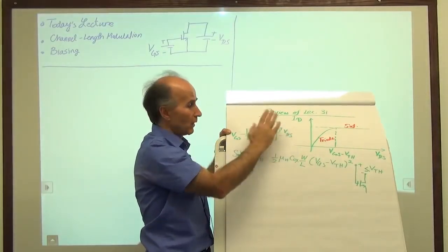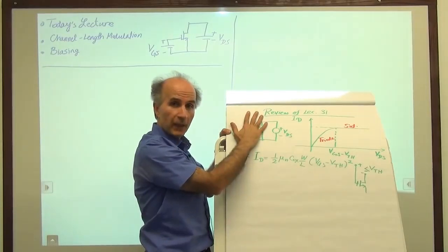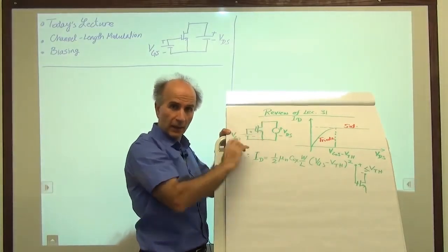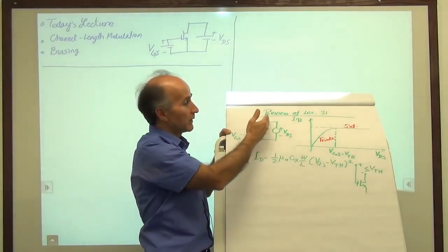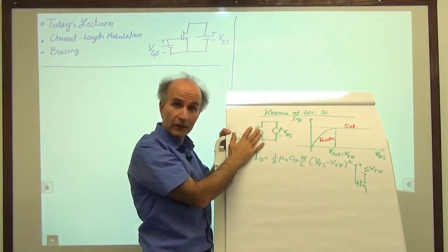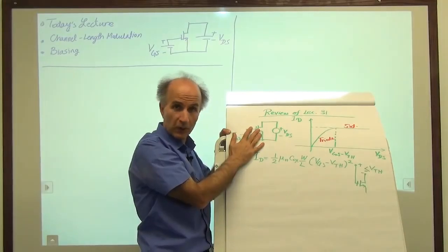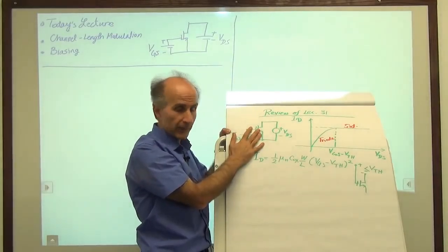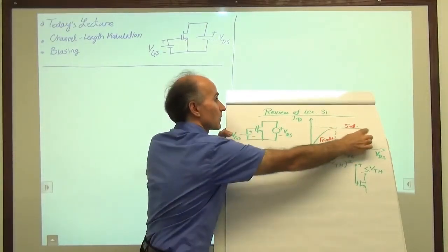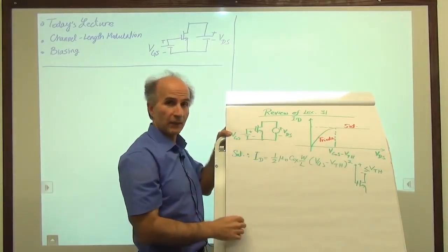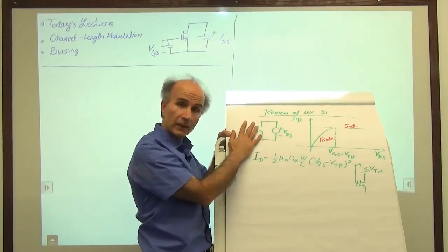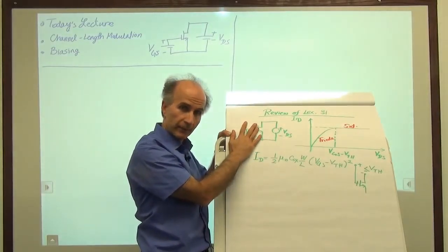So if you put this in a black box, it looks like a two-terminal device, again not worrying about the substrate and body and all that, and we see that it operates as an ideal current source, which means it has a constant current. So in this region, so long as we guarantee that VDS is greater than that value, the device can be approximated by a current source.